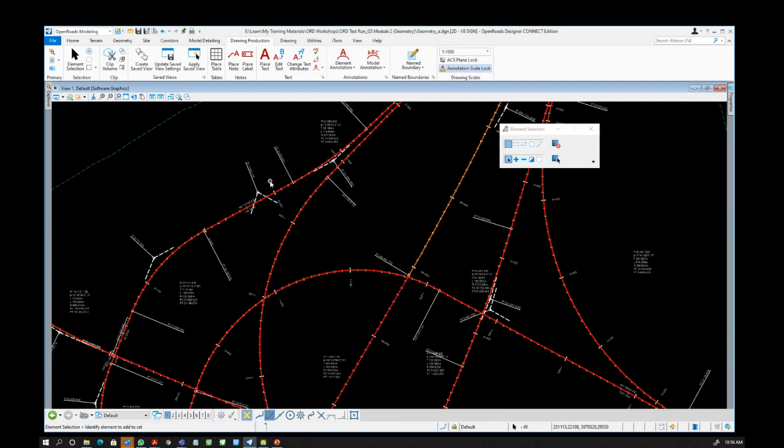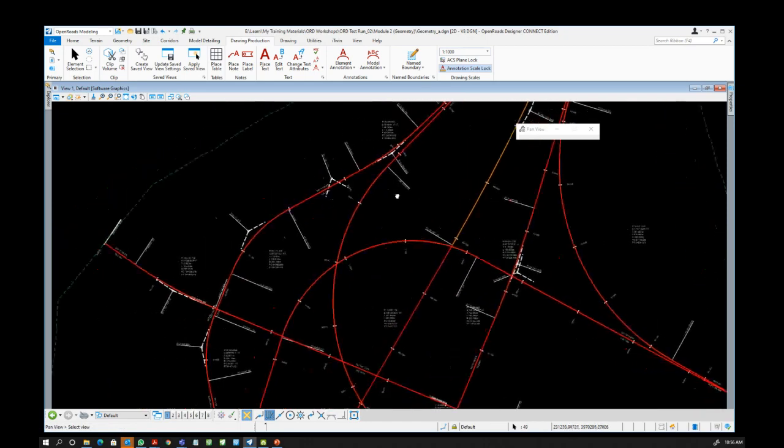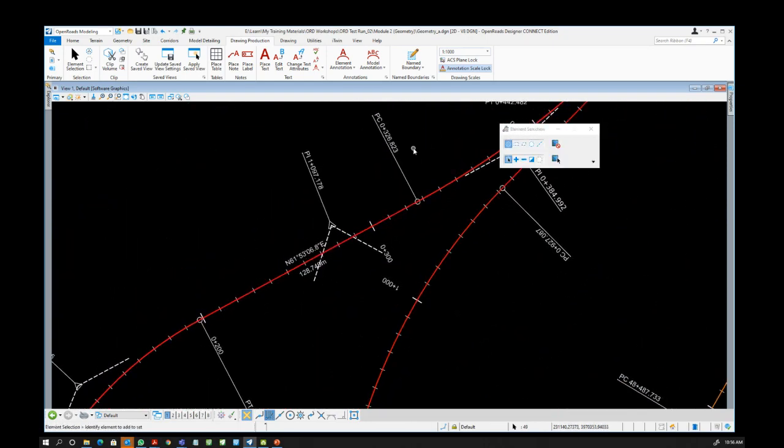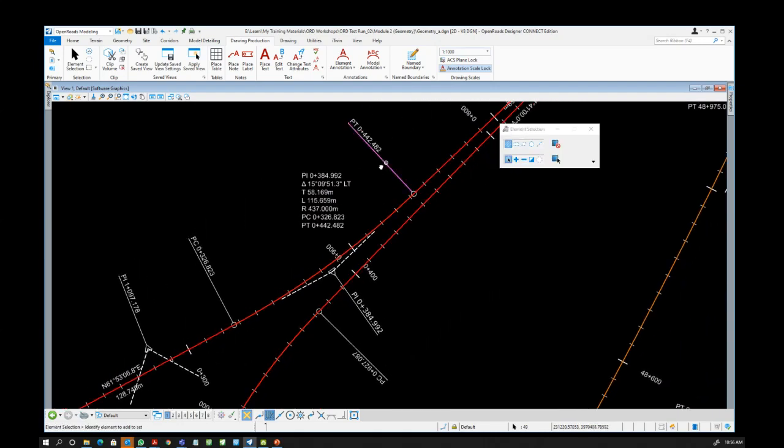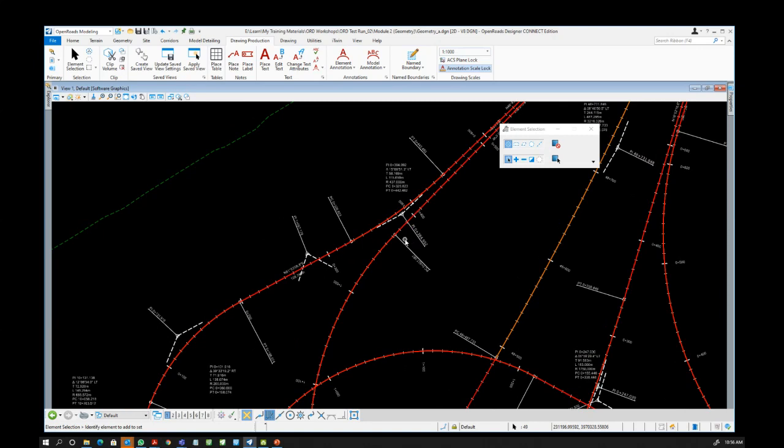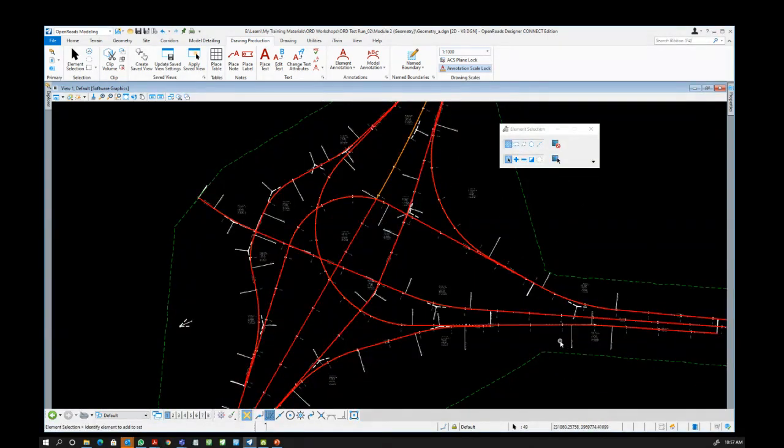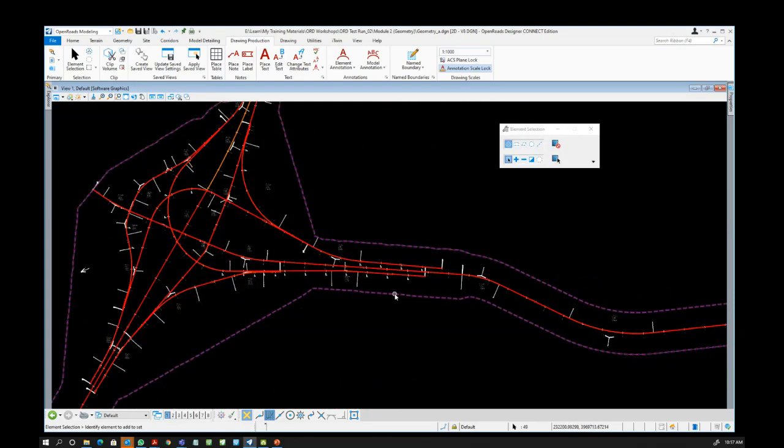Although it's a bit of a long story to tell, every feature definition that you assign will also affect what type of annotation the object will have. So for those who will be using OpenRoads Designer after this, hopefully you will have training or further exploration on setting your own feature definitions, which can be saved in your workspace, so that every time you just select the feature definition you would like and everything goes automatic. Are we clear?